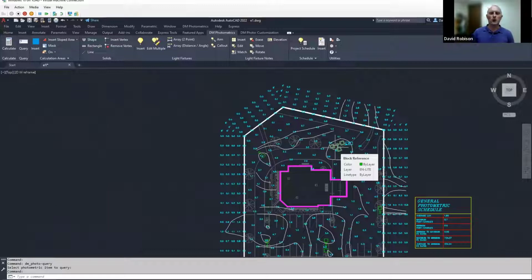And just as a warning, the more edges you put into the software, the longer everything takes. So don't go crazy with your curves. Have a few edges to it, but don't make it tons, because that can increase your calculation time. So just be aware of that.